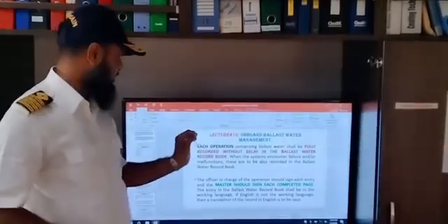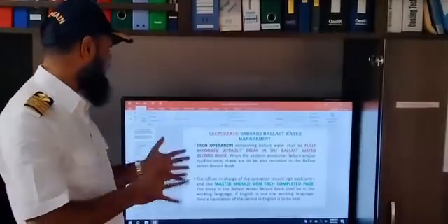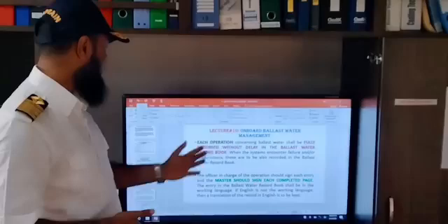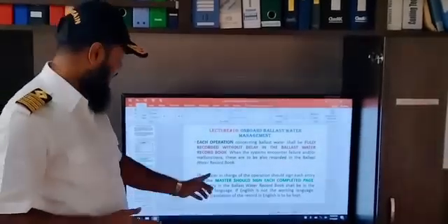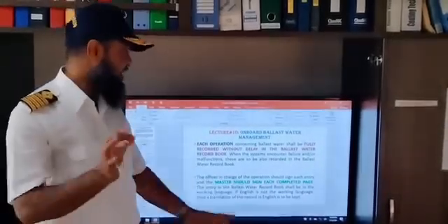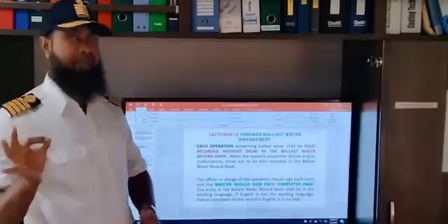Each operation concerning the ballast water shall be fully recorded without delay in the ballast water record book, and after completing the page, the master will sign the completed page only.